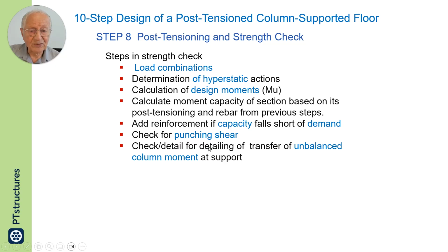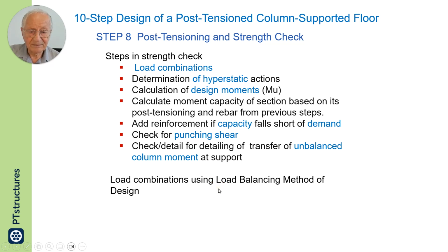After punching shear, we do some detailing. One of the detailing instances is to take care of the unbalanced column moment at the support. I will describe that in greater detail in the following slides.